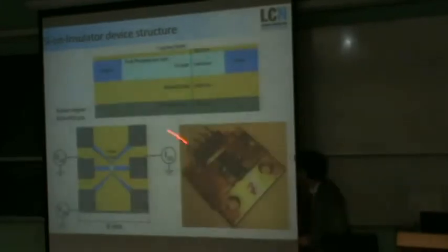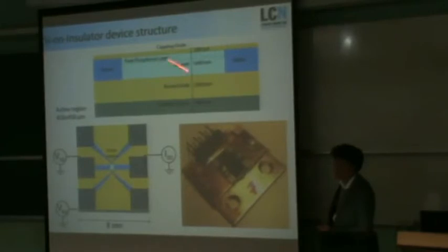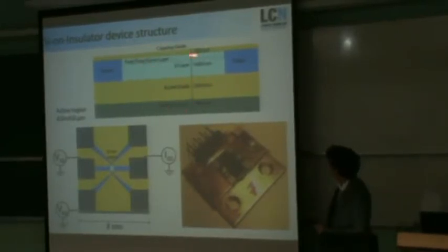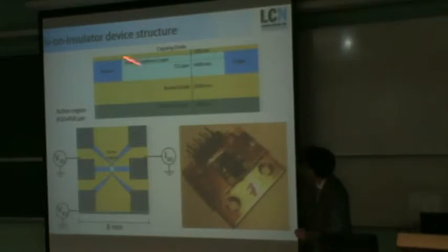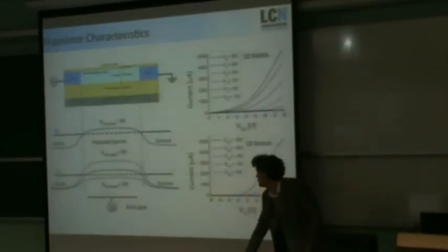If we look at the cross-section of these devices, they're made with silicon on insulator, with a silicon layer of 1.6 microns. On top of this was a buried oxide. We wired up these devices such that you could bias the handle layer and form a backgate. So really it's just a backgated transistor device, quite large in size. These devices are also implanted with a phosphorus layer in the top, so they have a high phosphorus content at the top surface of these devices, which is important later on.